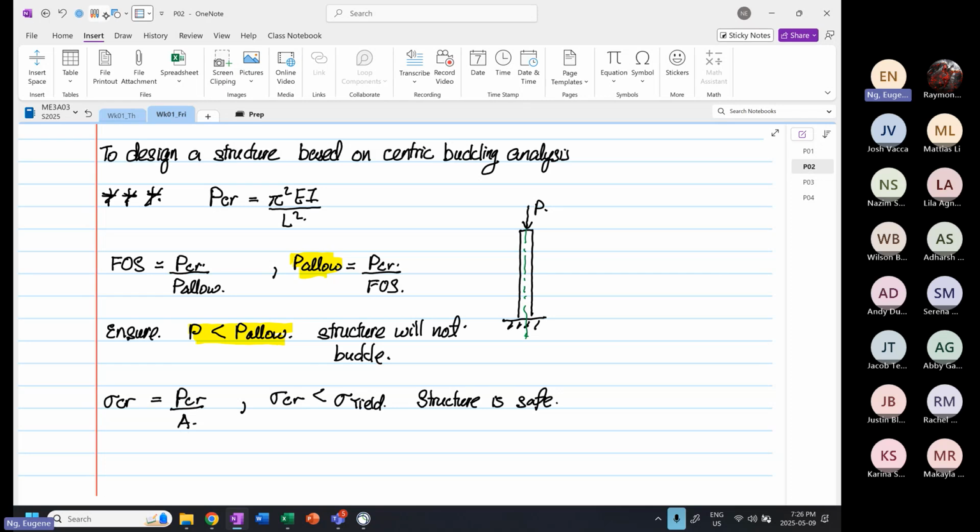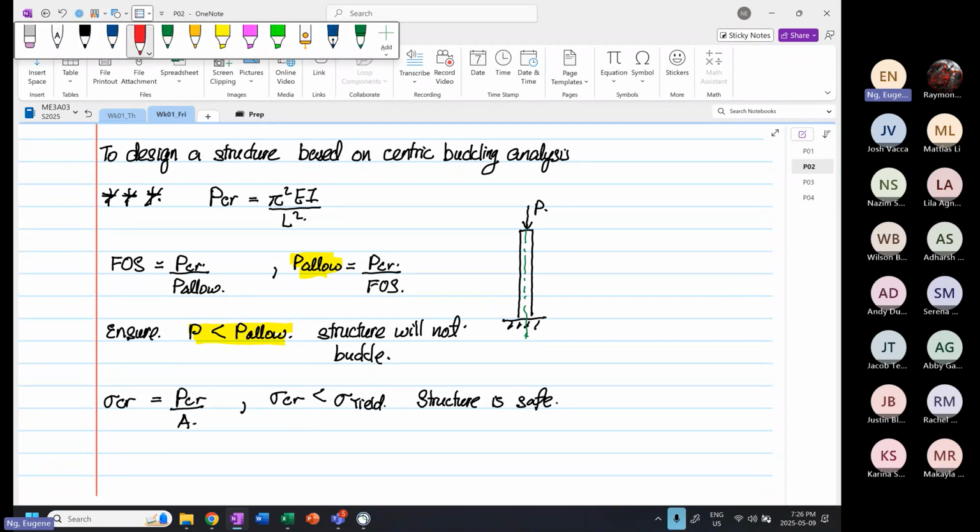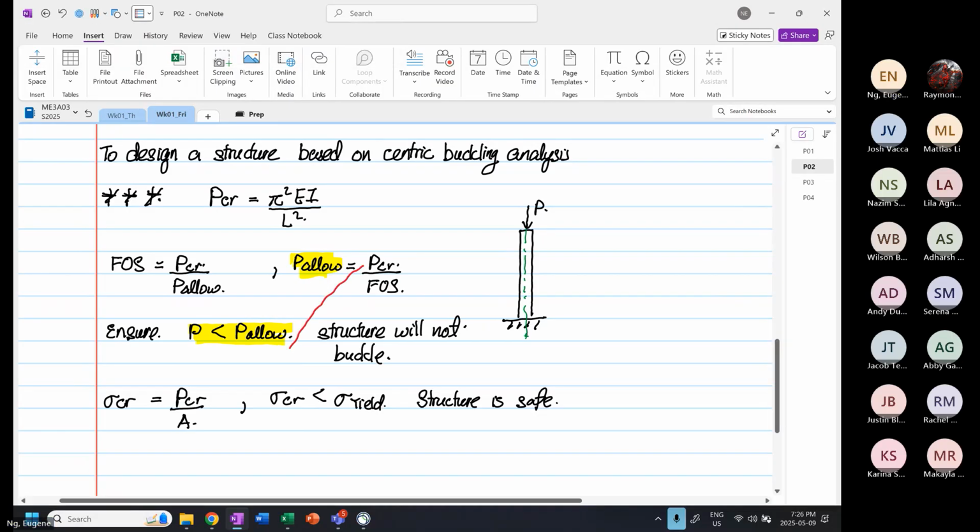The next thing that a lot of times, this is just for buckling. Okay. The stress critical, we have to use the what? P critical value and not the P allowable. Are we clear? Okay, so this is very unique for buckling, and you don't want to mess this up. In other analysis you use P allowable divided by area. For buckling we use P critical.